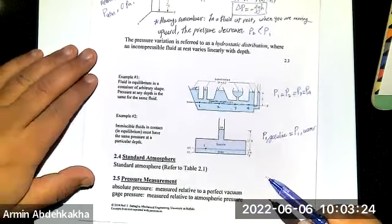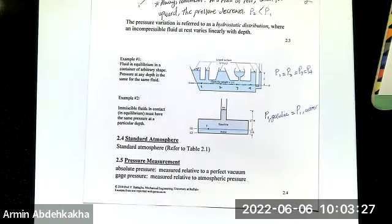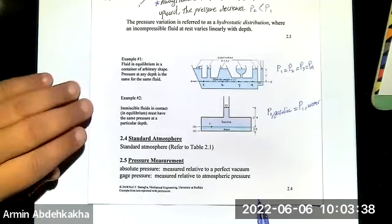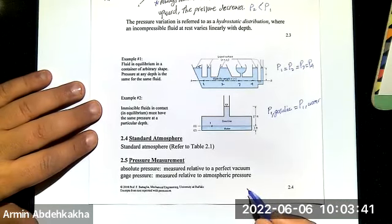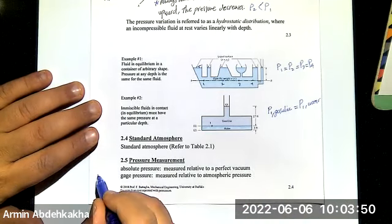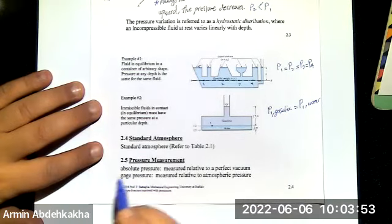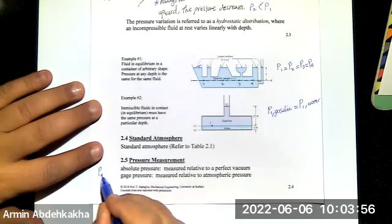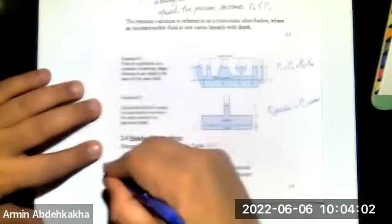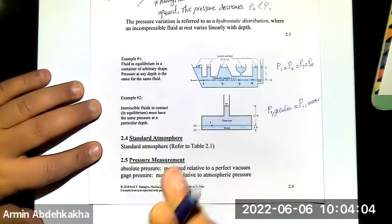The other thing is the standard atmosphere, which you also need for question 1 of the homework. This is also available in table 2.1. The other thing is the absolute pressure and gauge pressure. We already talked about it in the previous chapter. The total pressure is the absolute pressure, which is when atmospheric pressure is also considered.